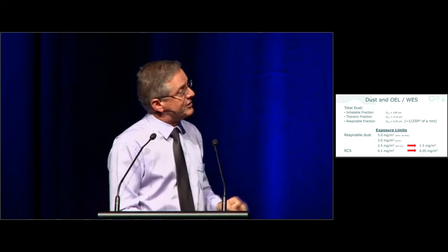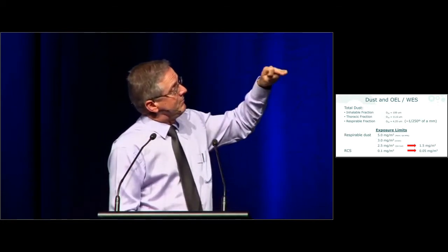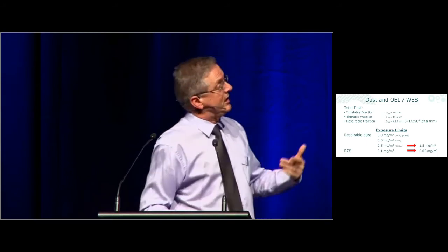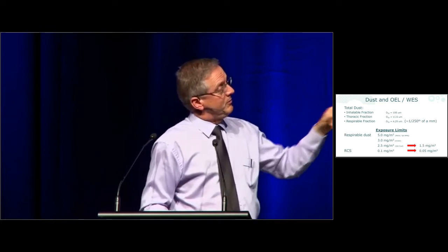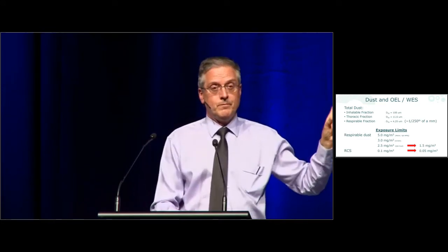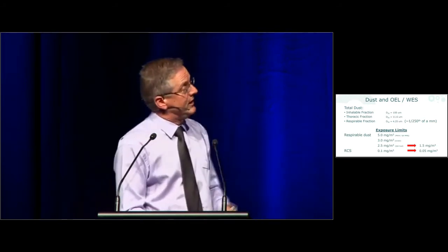This slide's a preamble into the next series that I'm going to have a look at with regards to filtration. Focus on dust size, so 1/250th of a millimetre. That's dust you just literally won't see. So a worker will think that they're in clean air when they're actually not. Those exposure limits are important, especially the bottom 2. When you look at the potential reduction, well, the last one actually, respirable crystalline silica is probably going to go down to about 0.05.